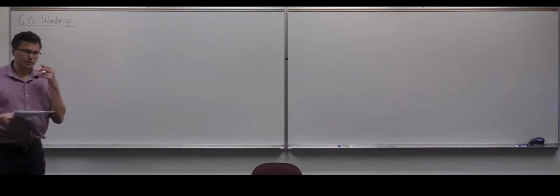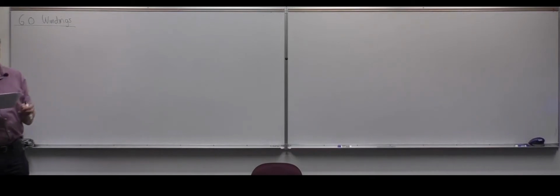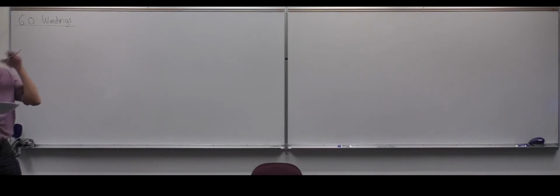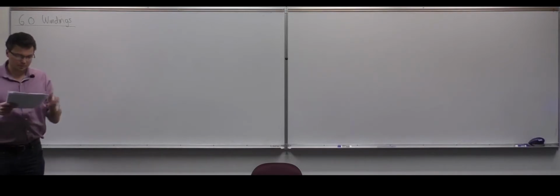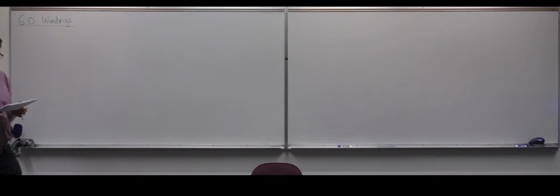And this is really important because in a lot of machines you can end up with a lot of torque ripple if you're designing it. Understanding how windings affect the harmonics within the air gap is really important if you want to design an electric machine, or if you want to understand in more detail how the electric machine works. So I just thought I'd do a little recall.